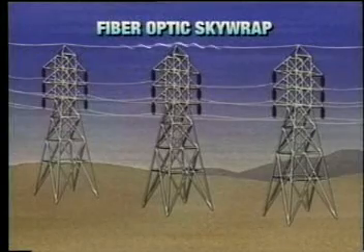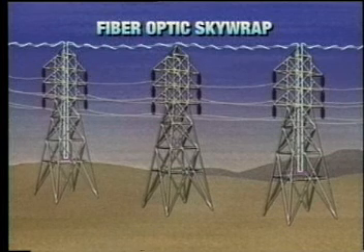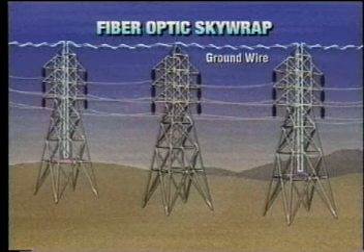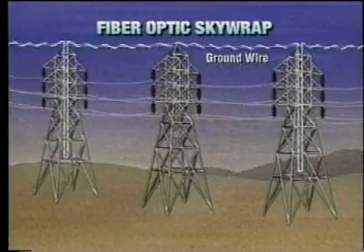One innovative aerial installation technique for utility use is wrap-over phase. It is used as an alternative to OPGW on structures that already incorporate a static line. Fiber optic cable is wrapped around the ground line or even a phase conductor, eliminating the need for a lashing operation. Because the cable is all dielectric, lightning strikes are unlikely to damage it.